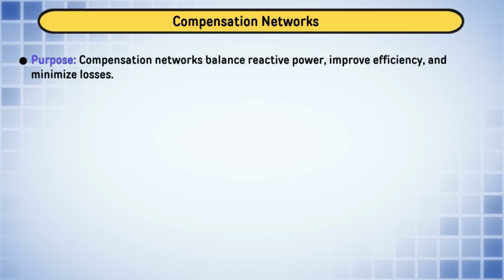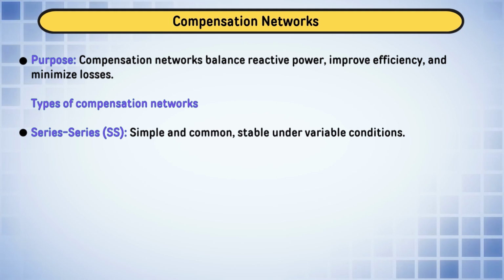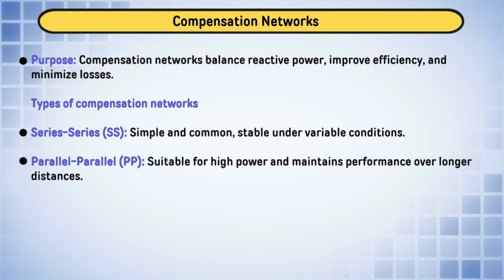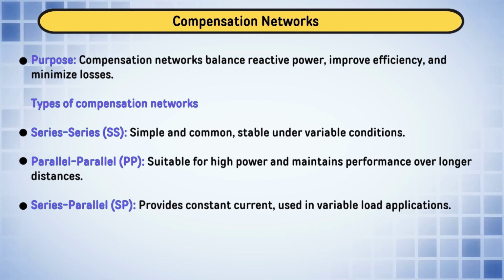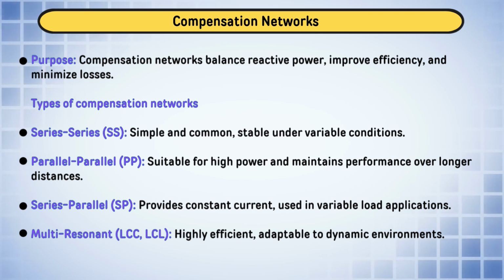Then finally, people are using disturbance observer based control, which improves the control performance by estimating and compensating for system disturbances. Challenges in converter control: disturbance rejection, voltage ripple, current control, and dynamic performance under V2G and G2V mode.